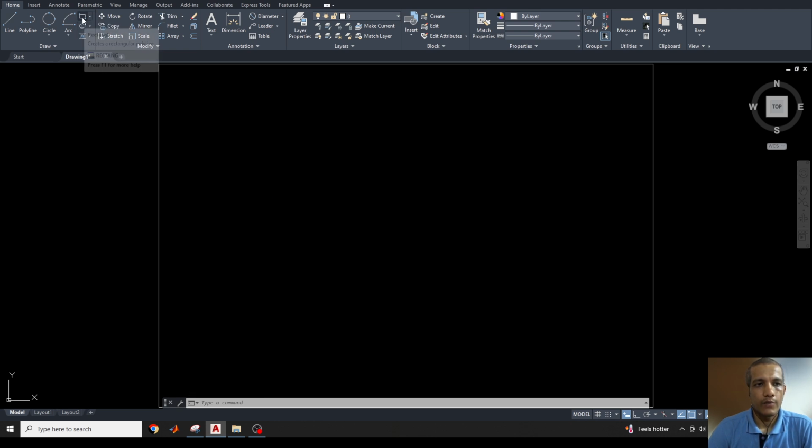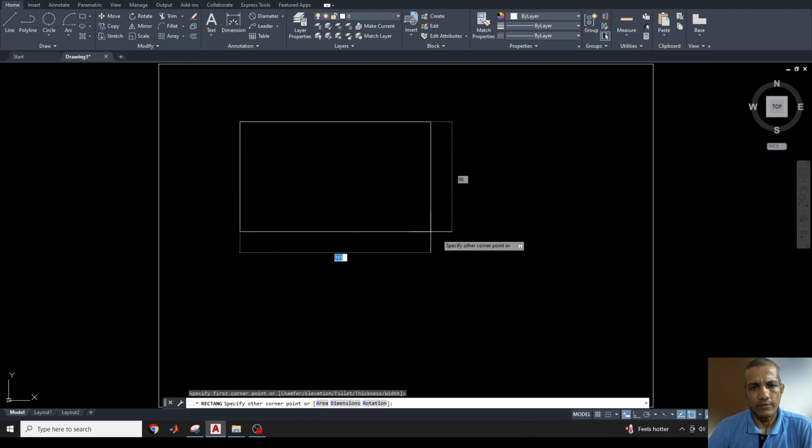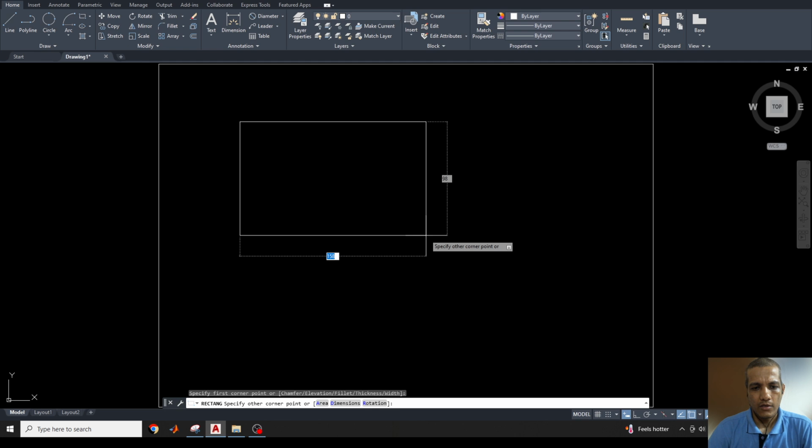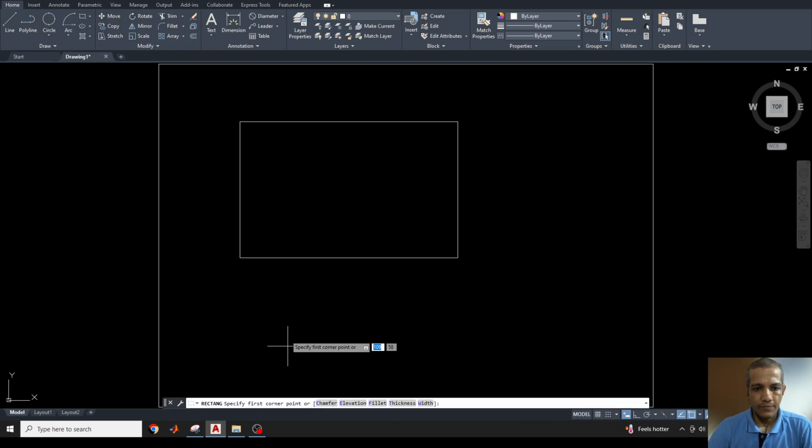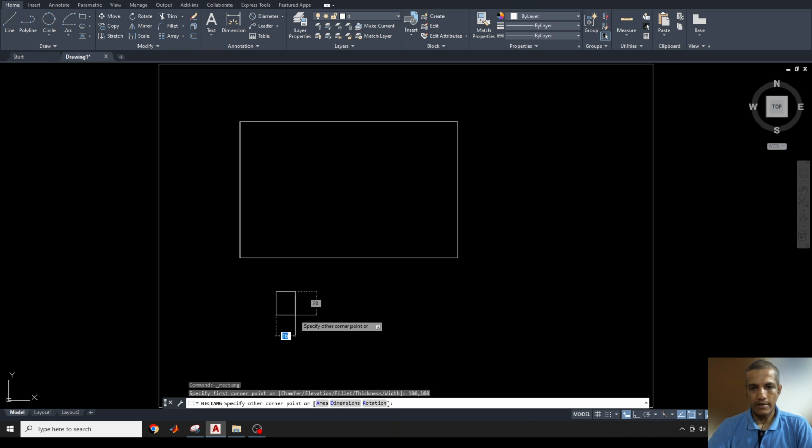So this is the polygon option. Now in the rectangle, directly you can go for the rectangle. We need to specify the first point and specify the other point. Easily you can draw. Or else, similarly, rectangle, specify the first point. We can click on the screen, or else we can give the X point and Y point. Like suppose again I will give 100, tab 100, enter.